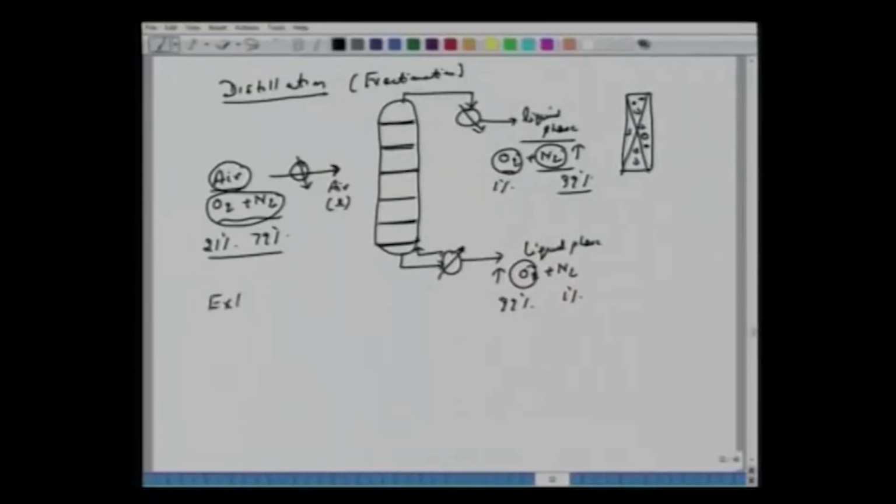So as we said, for whatever unit operations we have, we have very extensive discussion on the mass transfer aspect. Wherever required, we will have the heat transfer aspect. Okay, so let's continue and give another example of another unit operation here, extraction. Just like we have absorption and distillation, we will have discussion on extraction. Now what is extraction? Sometimes this is called liquid extraction. It's also called solvent recovery, LLE.